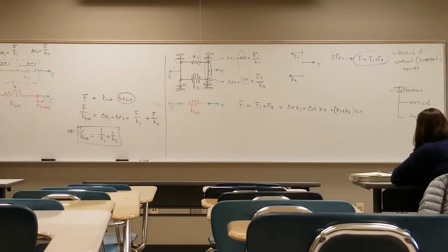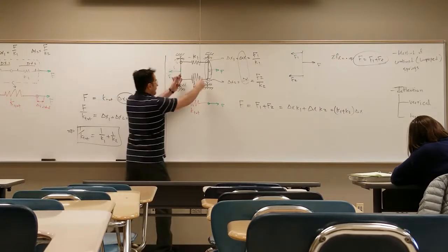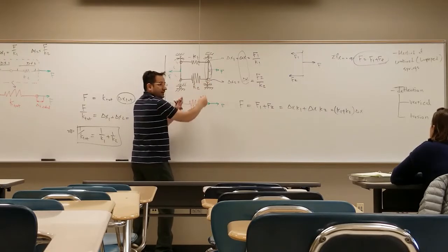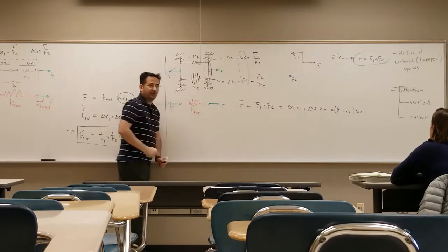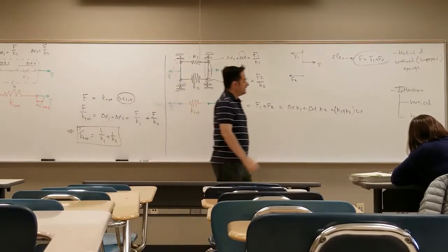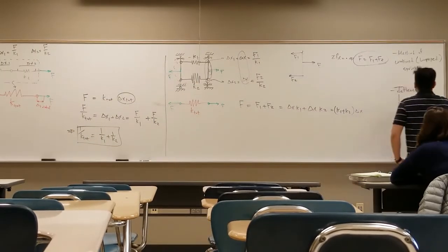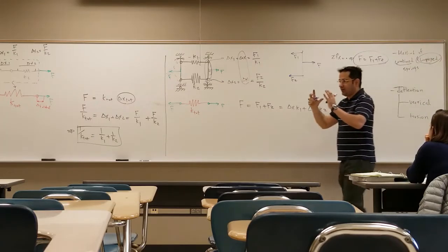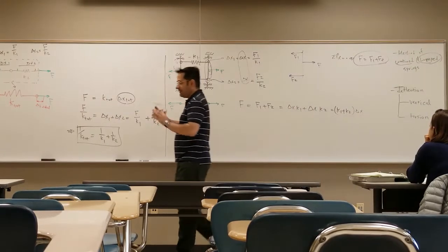The same delta x, because we're trying to replace this configuration with a spring that is going to mimic it, so it has the same delta x with the given force. That's the method of combined or lumped elements, which mimics the original system exactly.